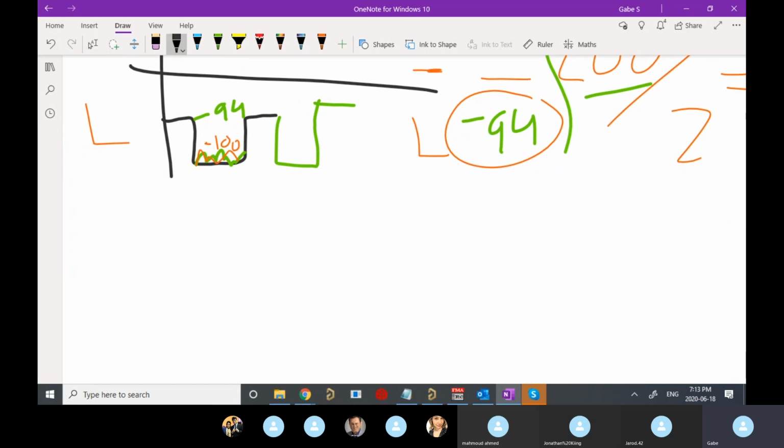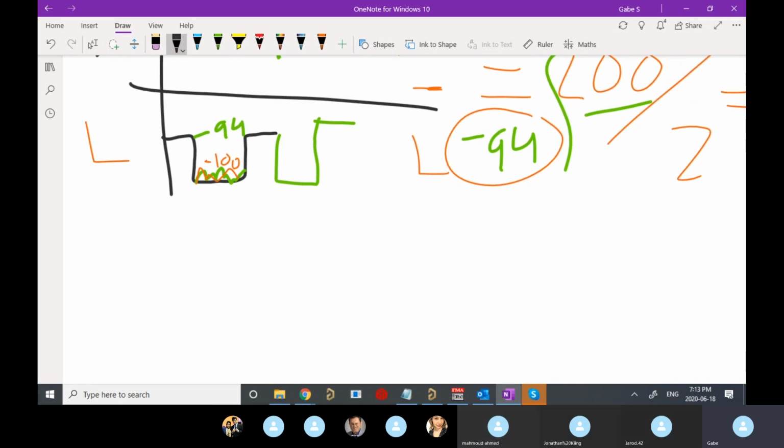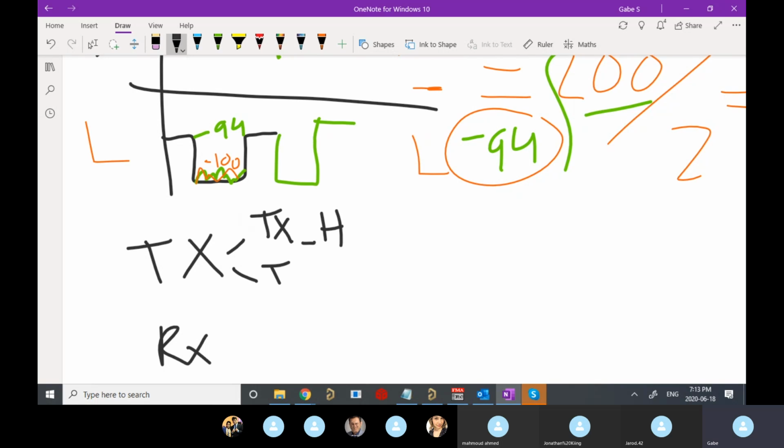Yeah, so are the 2 RX ones identical? Like the exact same signals on both? Yeah, like it's differential, like plus and minus. Nice, exactly. So that's a really robust UART, right? You have a TX and RX still, but now it's split into TX high and TX low, or TX plus and TX minus, right?